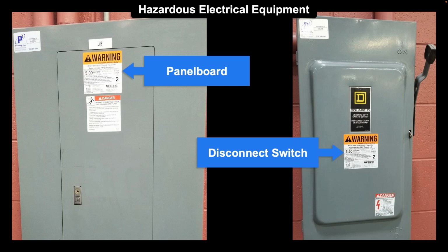Even in these pictures, there are other labels that say danger and show some basic electrical hazard information, like, hey, this could hurt or kill you, you should follow 70E requirements. That's not what we're talking about. Those are the manufacturer shock labels that don't have boundaries. Yes, there's a shock hazard present, but if it doesn't have the right information that our labels do, there are no specifics. If there are no specifics, that doesn't count. If it's just a general warning, that doesn't count. You need to know how severe the hazards are and how far out the boundaries go so that you can protect yourself accordingly.